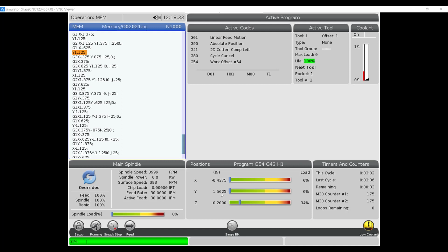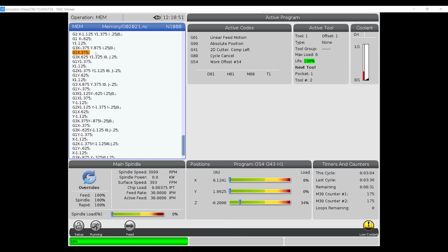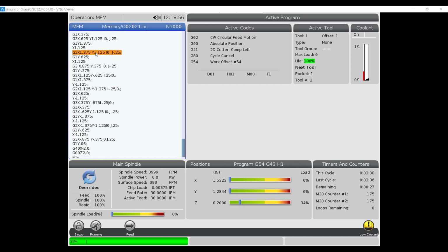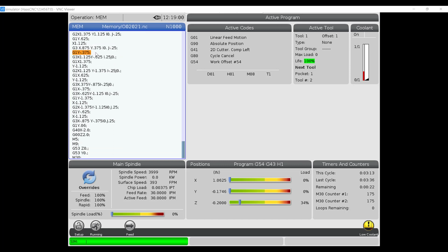All right, you'll see a 0.4375 when there's a 0.625. Okay, so we're supposed to be going to minus 0.625. That's the edge of the cutter. If we go 0.625 minus 0.1875, you get 0.4375. So it goes all the way around this workpiece using cutter compensation. It did the same thing before whenever we're using it. So whether we compensate the D1 value of 3/8, which is going to be half of it, the 3/16, or it's going to be compensating the D21 value that's 20 thousandths bigger on diameter, it's the same.